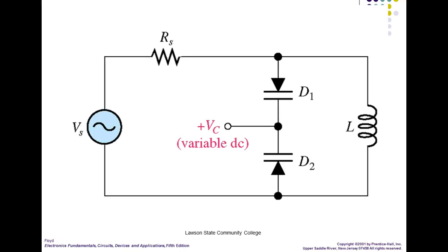This is another tuned circuit. But this would be the actual way it would work. So to get a true tuned circuit, we combine a capacitor with an inductor. And what happens is these guys, so X sub C is equal to 1 over 2 pi F C. X sub L is equal to 2 pi F L. And these guys are just opposite of each other.